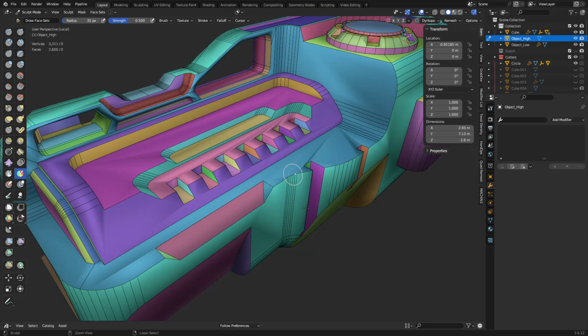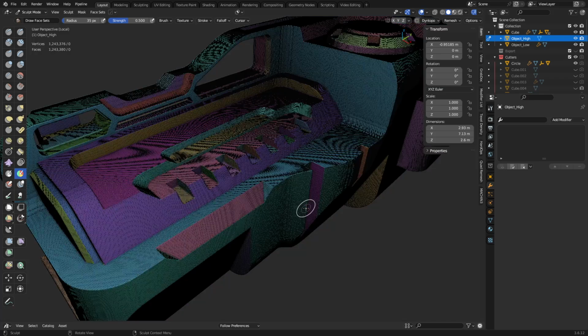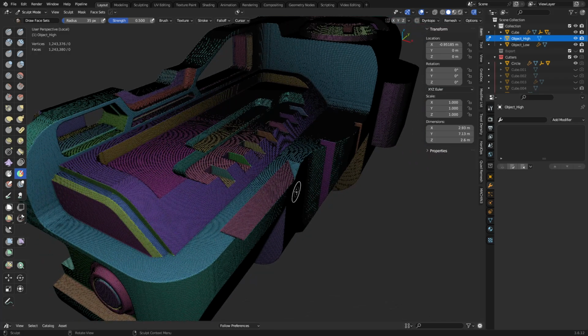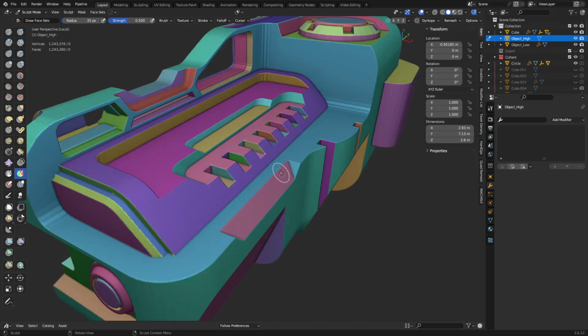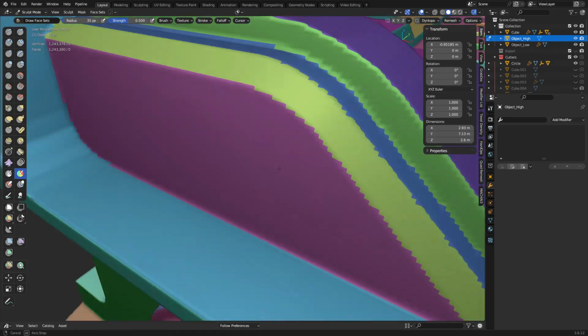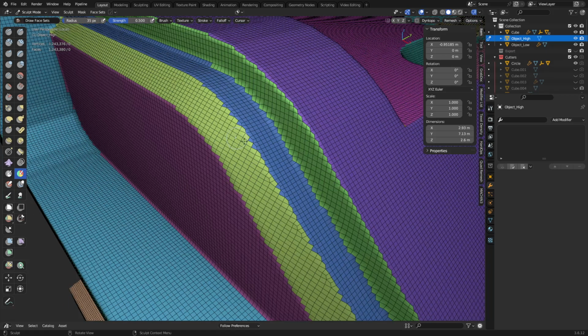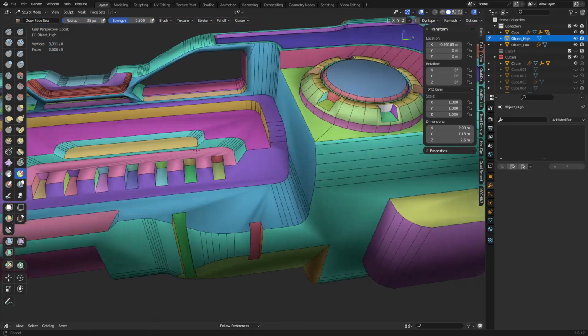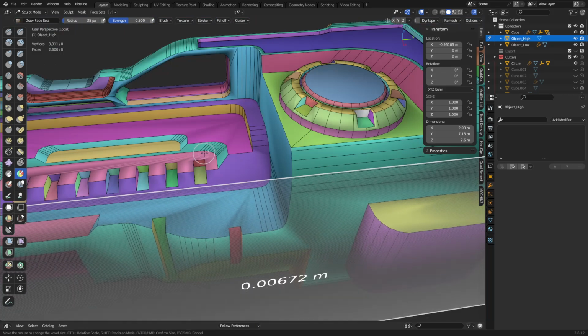Okay. Depending on how big your object is, you can only go down so far with a remesh, right? So you might need to increase the size of your object so that you can reach a smaller number. So you apply your scales and upscale your stuff, I guess. But you'll see here, perfect results. No, it's not very dense at all, actually. Let's try, we'll go down a little bit further to like 0.06, 6 millimeter.